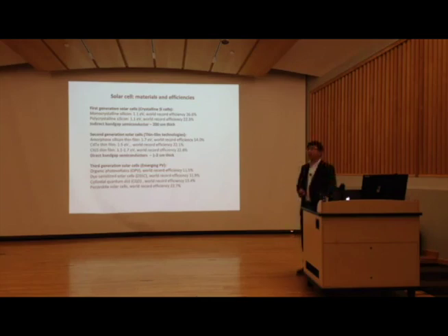And does ambient temperature have much of an impact on efficiency of the panels at all? Yes. Temperature did have an impact on the efficiencies. When people report all these efficiencies, you have to do the measurement at, I think, 25 degrees. If you do the measurement at different degrees, the efficiency is different. Usually at lower temperature, the efficiency is higher, but not much difference. It's not like, maybe at 0 degrees, the efficiency can improve 1%, something like that. There is some impact, but not big.